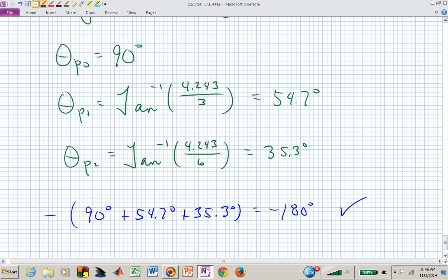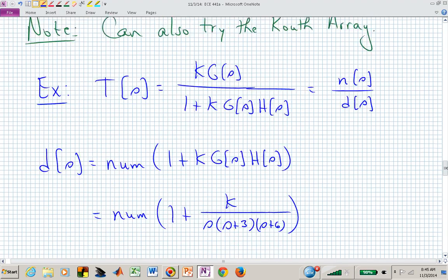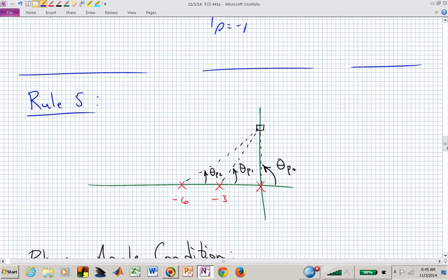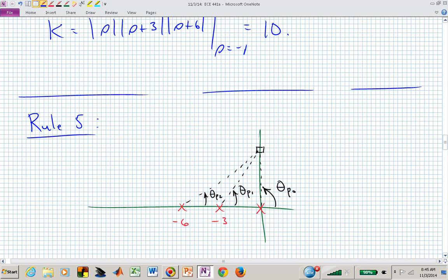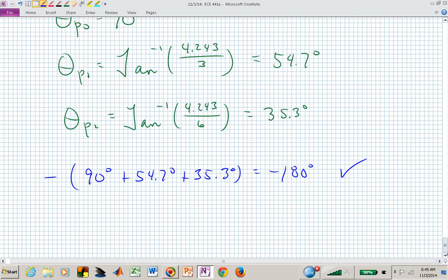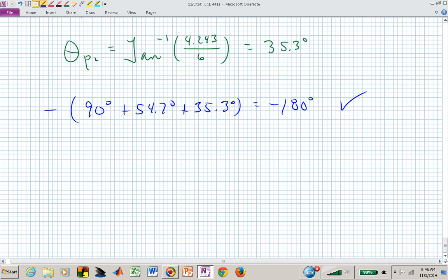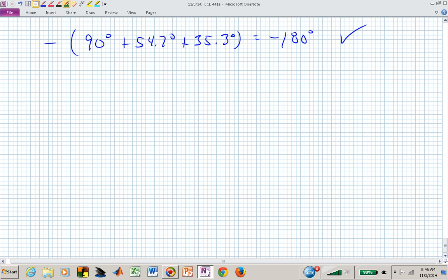So we've now verified those. If somebody was doing it the original way, hopefully you wouldn't stumble around too much. You would calculate the trig and say, there's where my asymptote crosses. You would maybe drop down a little from that and find out if you were close as far as where the branches cross. So now we have a good picture of the root locus, a pretty accurate picture.